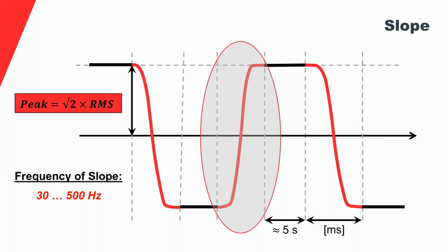And what pretty much was done was that the test results were compared to damped AC. And since damped AC was already proven to be comparable to power frequency, then the logical conclusion is cosine rectangular is comparable to power frequency. So you get the same partial discharge inception voltages, and in principle the same activity.